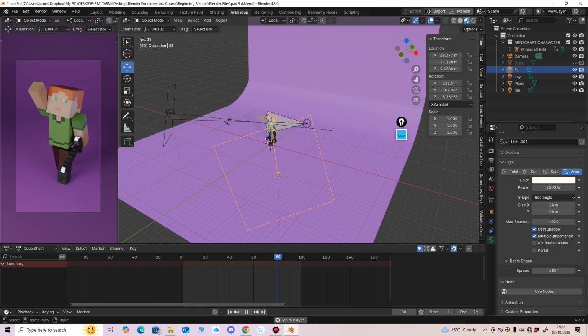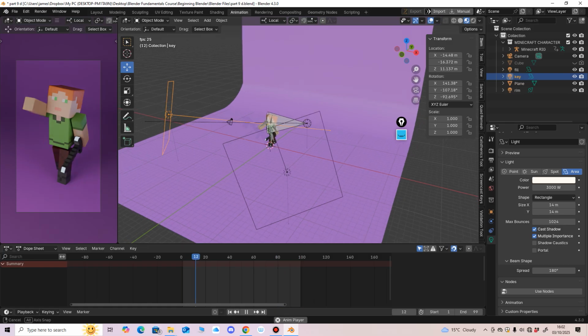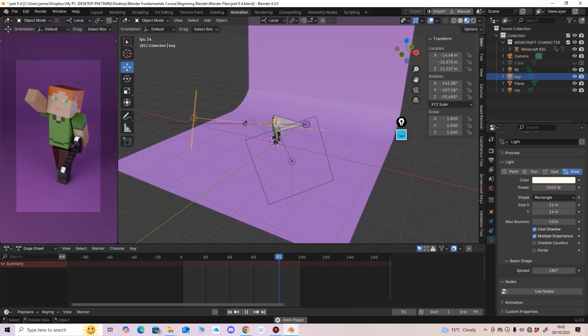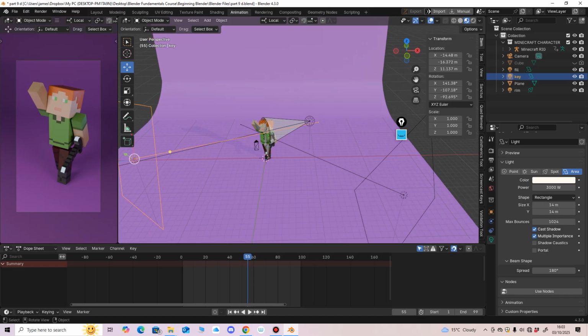Play more to get the shadows, less or more, less harsh. It's a touch too harsh at the back. So let's maybe bump that up to 14. Let's reduce the harshness there. Not much of a shadow there, a bit of an infinite background there. Bit of a gradient. He's waving. You got a bit of a pulsation on the sword. So let's just choose a random frame where he's waving. He's got his hand up there. Let's just hit F12.